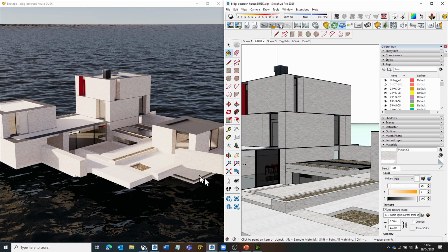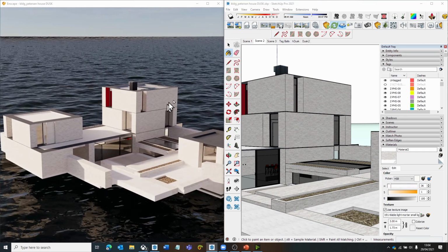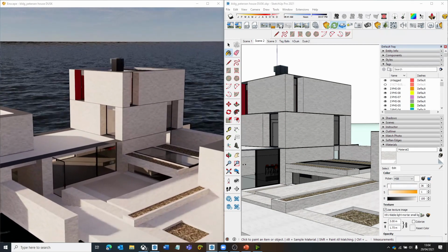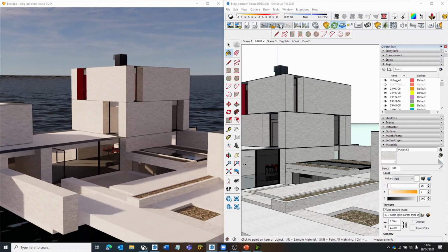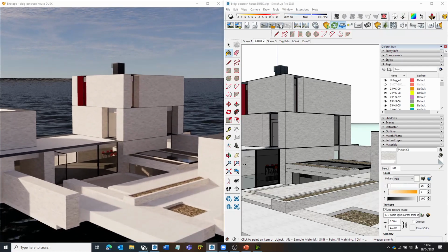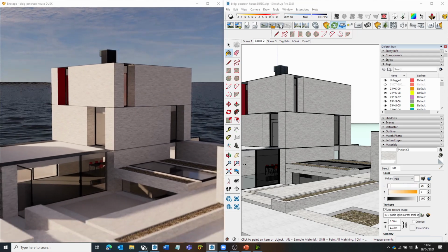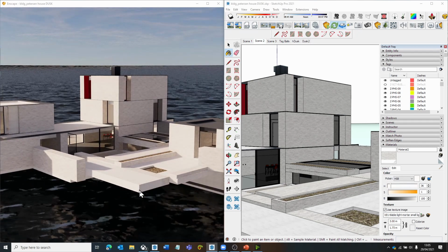Never mind. Right. What we're going to have to imagine is, when we've color dropped this, essentially the brightness value should be the average of this here, and it should be 84%. 84, as we've talked about earlier, is actually brighter than a piece of white paper. So actually our brick is not a light colored brick. It is actually a white colored brick. And this is how the rendering engine is having to deal with it. It might not necessarily look like a white colored brick because the auto exposure and other stuff is going crazy trying to deal with it, but it's actually causing glitches in the way that lighting is rendered within our model.